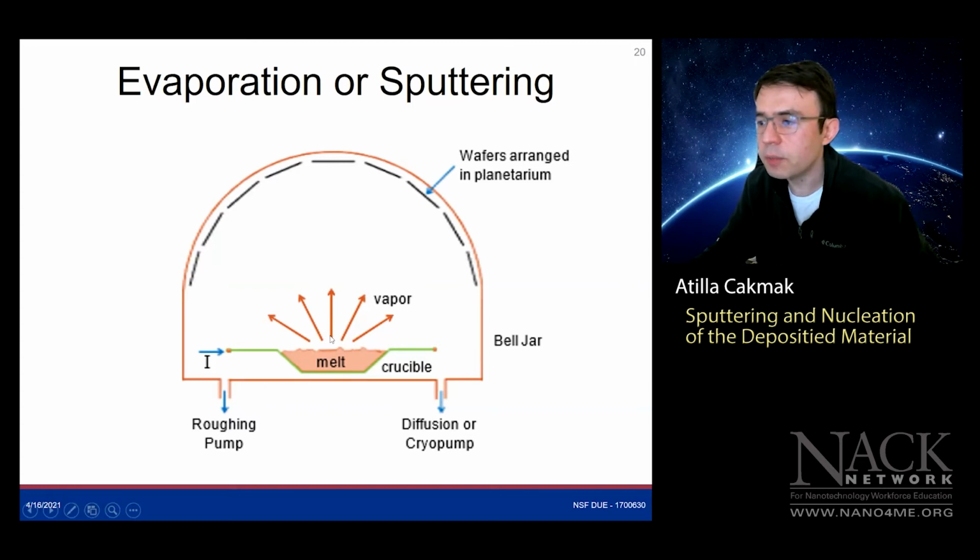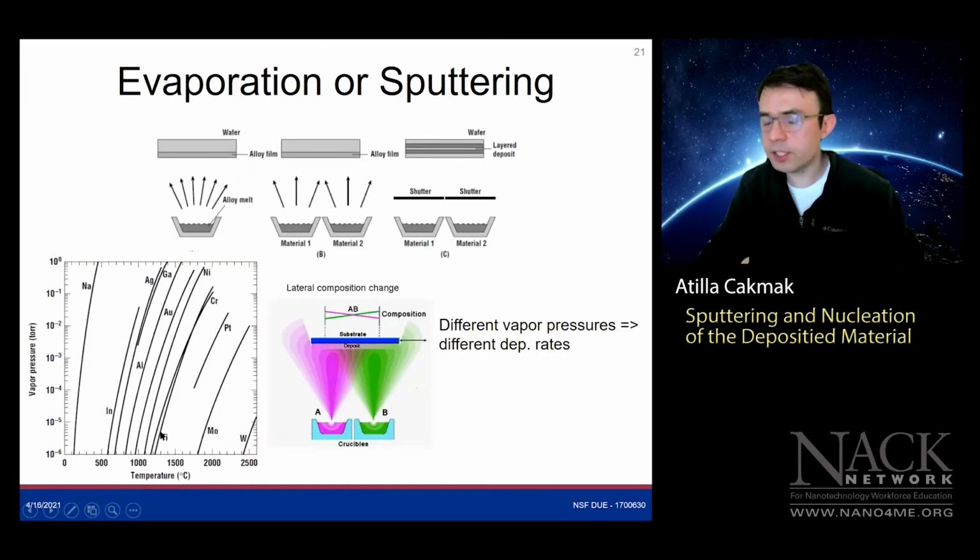I'm going over these drier discussions quickly, but now let's discuss evaporation and sputtering before we go with Rich in some 20 minutes or so. We covered evaporation as the first deposition in the series. What was evaporation again? We're just putting some material inside our crucible, heating that up, and trying to put that evaporated material on our wafers, right? That was also happening in a chamber.